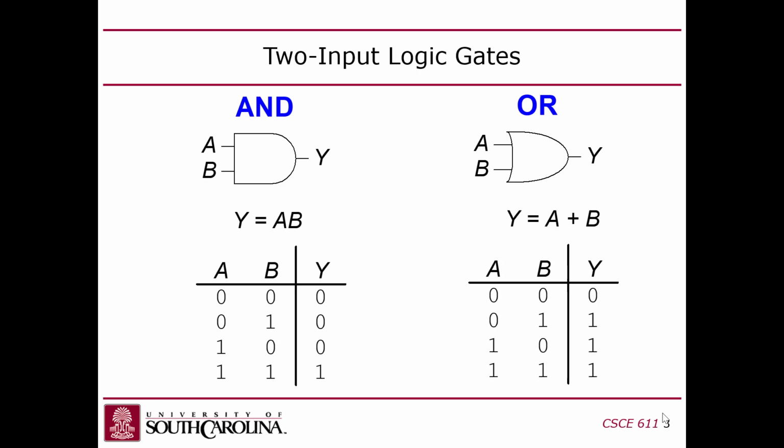And the depth isn't 4, but there's 7 inputs on modern FPGA LUTs. So there's 2 to the 7th power entries in this RAM that comprise the truth table. So there's 128 entries. So an FPGA is comprised of 128 by 1 RAMs, 128 entries deep by 1 entry wide, that comprise these logic gates. And when you fill those RAMs in, you're filling in the truth table.